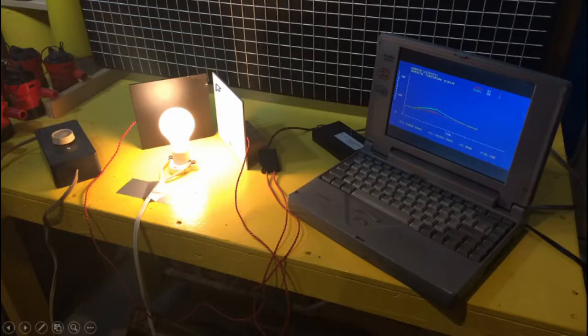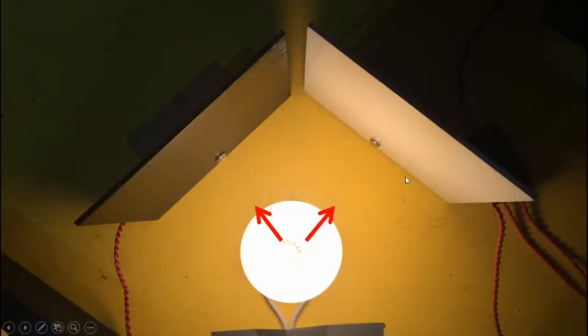I have my test plates here, one black and one white, and my heat source, which is my incandescent light bulb, and the temperature is feeding into the computer so I can look at it as a function of time. Now it's important in this experiment to have the plates equidistant from the light bulb, so they're receiving the same amount of thermal radiation. Now as the light bulb heats up, it radiates against the white plate, and it radiates against the black plate. What we want to do is see if the temperatures of these plates are the same.